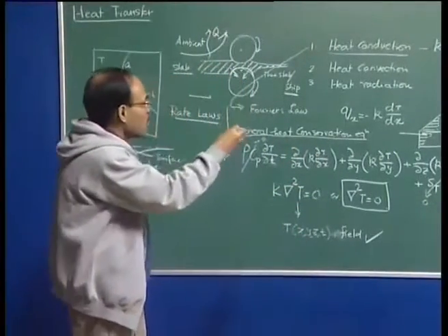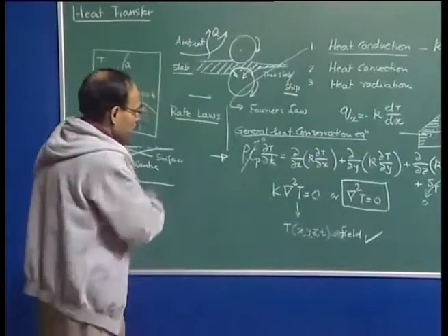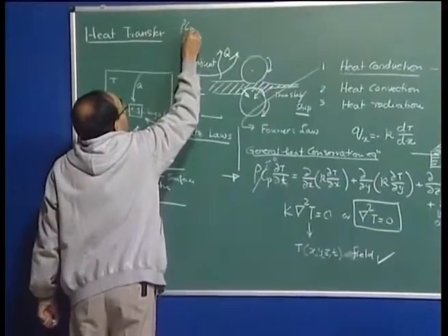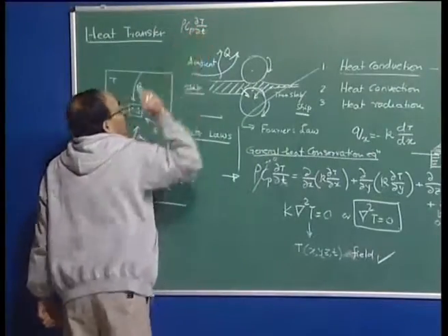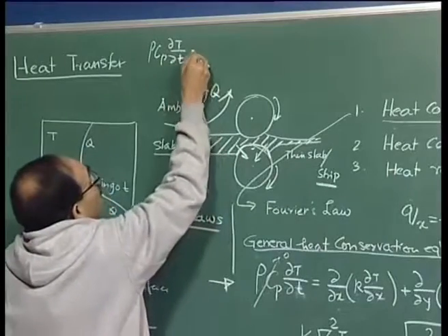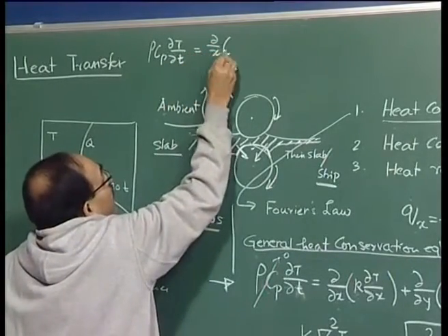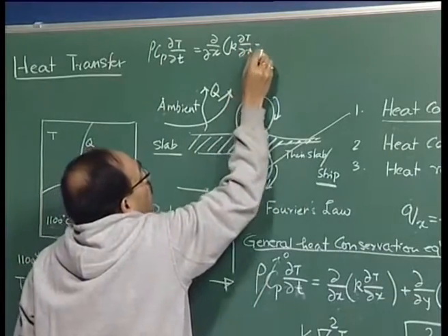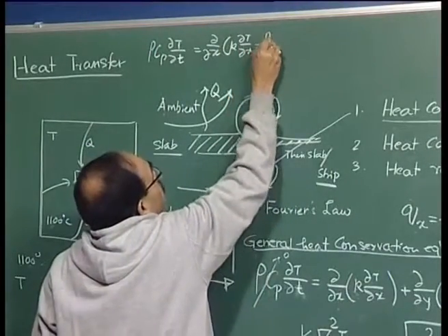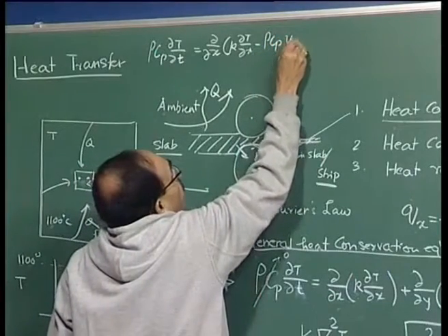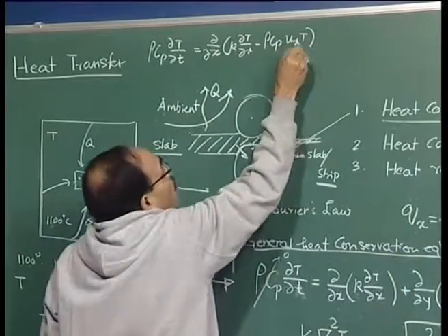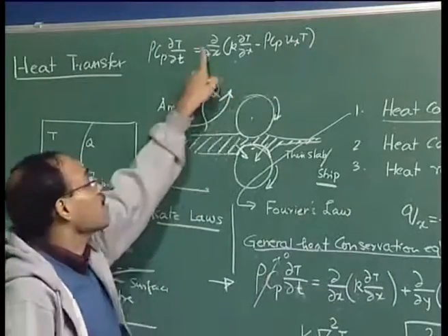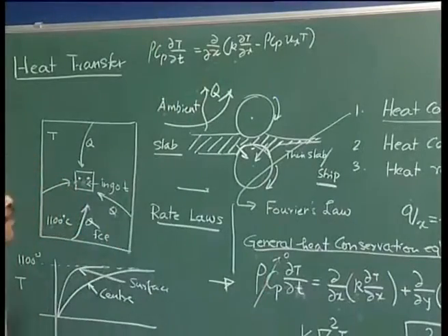And now, once I write the equation, you will be able to appreciate the similarities between conduction and convection. So, let me just write down. I have the same term rho Cp, this is the accumulation term, then we basically write it like this. So, we have this, which now represents the net heat flux. This is the conduction heat flux, this is the convection heat flux, and this represents the net heat flow due to conduction along the x direction.